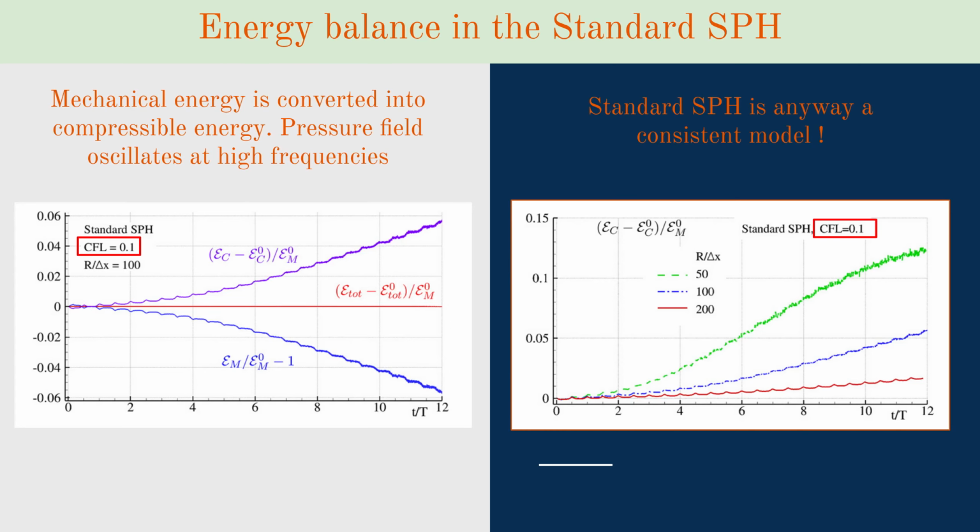If we now increase the number of particles, the unphysical particle motions are progressively reduced. From a theoretical point of view, SPH is a consistent method, and therefore it converges toward the correct solution. However, this convergence comes at the price of very large and often impractical computational costs.